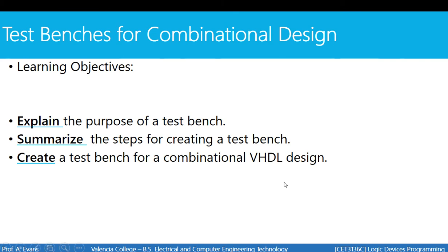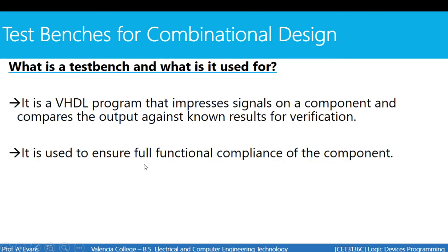And we're going to spend the bulk of this video today typing up our first test bench for a half adder. First of all, what is a test bench and what is it used for? It's a VHDL program that impresses signals on a component and compares the output against known results for verification. So basically, a test bench is written to verify the design of a particular VHDL architecture.